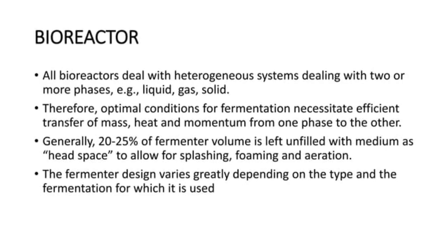Bioreactor. All bioreactors deal with heterogeneous systems involving two or more phases, that is liquid, gas or solid. Therefore, optimal conditions for fermentation require efficient transfer of mass, heat and momentum from one phase to another. Generally, 20 to 25% of the fermenter volume is left unfilled with medium as head space to allow for splashing, foaming and aeration. The fermenter design varies greatly depending upon the size and the fermentation for which it is used.